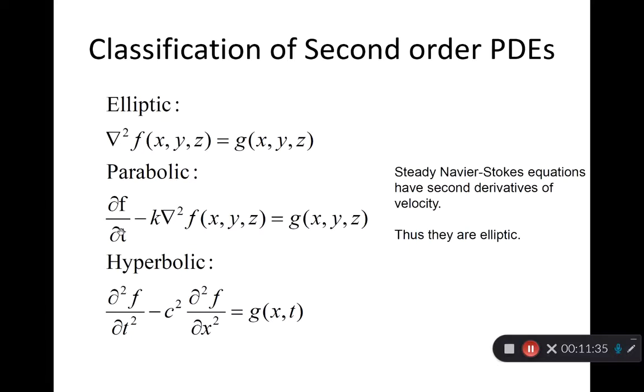There are other types of partial differential equations. If you have a time derivative, it's called a parabolic PDE. Parabolic means you can march in time, or in this direction. So in CFD, we will solve this problem by adding a time derivative and forcing it as an unsteady problem. Start with some random initial solution for U, V, and W and pressure. Then keep marching in time until this df/dt goes to 0. When things stop changing, then we have recovered the original equation.